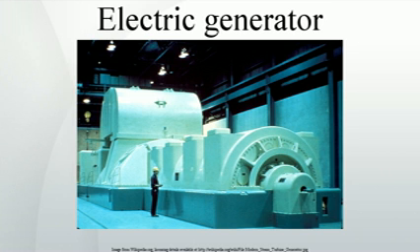Engine generator. An engine generator is the combination of an electrical generator and an engine, or prime mover, mounted together to form a single piece of self-contained equipment. The engines used are usually piston engines, but gas turbines can also be used. And there are even hybrid diesel-gas units, called dual-fuel units. Many different versions of engine generators are available, ranging from very small portable petrol-powered sets to large turbine installations. The primary advantage of engine generators is the ability to independently supply electricity, allowing the units to serve as backup power solutions.